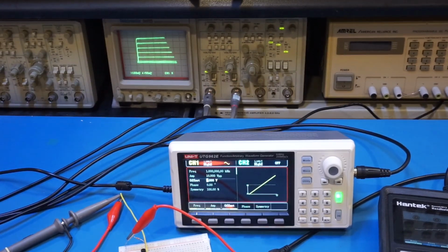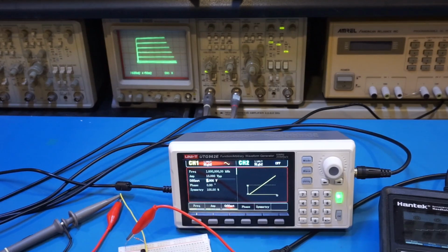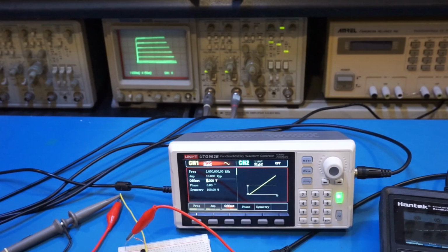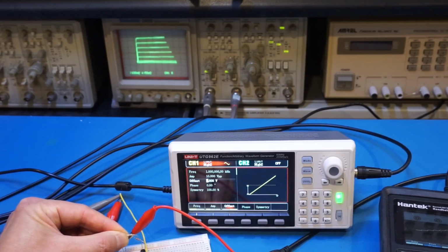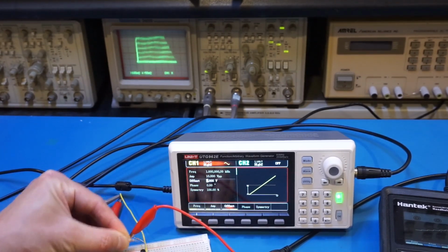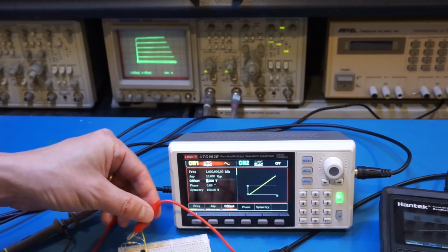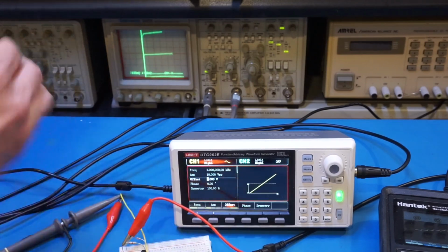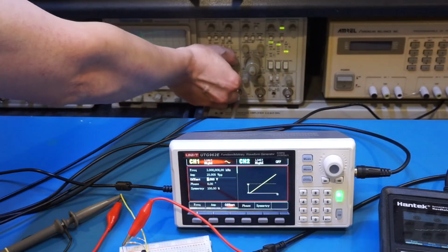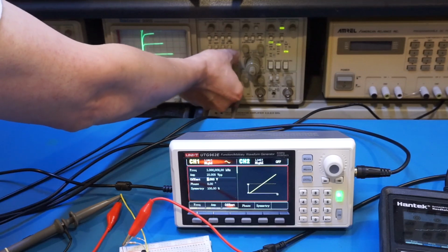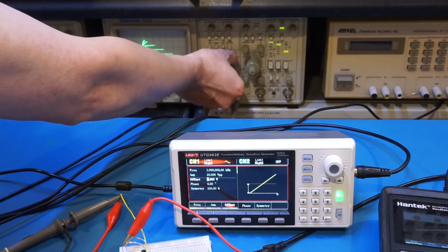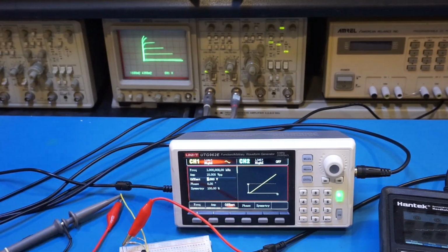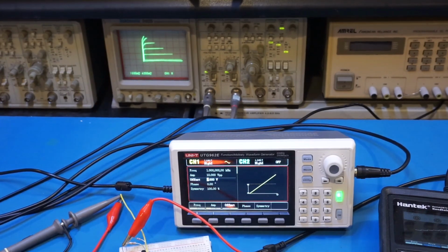Of course, if we change the base resistor value, we will get a different set of curves. So right now the base resistor is at 46 kilo ohm. So let's put in a 10 kilo ohm resistor and see what we got here. So let me switch this to the 10 kilo ohm. Of course, now the y-axis is out of the range. So let's turn it back down a little bit. And as you can see, now we have a different set of characteristic curves.